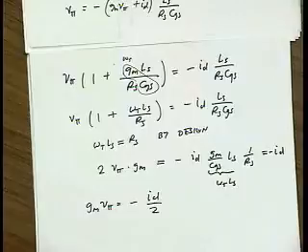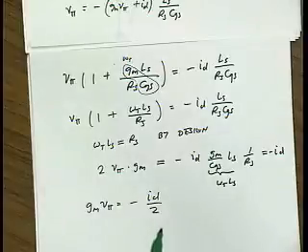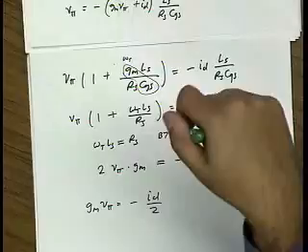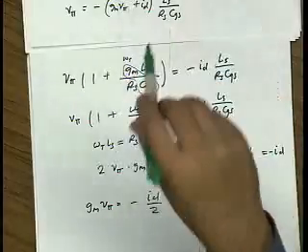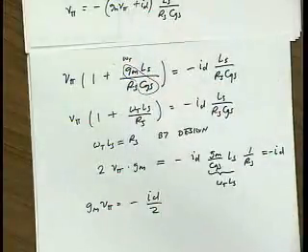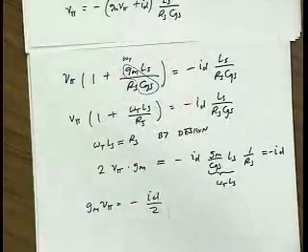Okay, any questions? Yes? In the previous cases, we were doing something to find the optimal source resistance and then match it for noise. Here, we are not making any attempt. We'll do that. The first time we have already taken Rs equal to omega t Ls, like it's a power match. So what we're going to do is calculate the noise figure of the inductively degenerated device, okay? And then we can optimize it just like we did for the common source device. Okay.